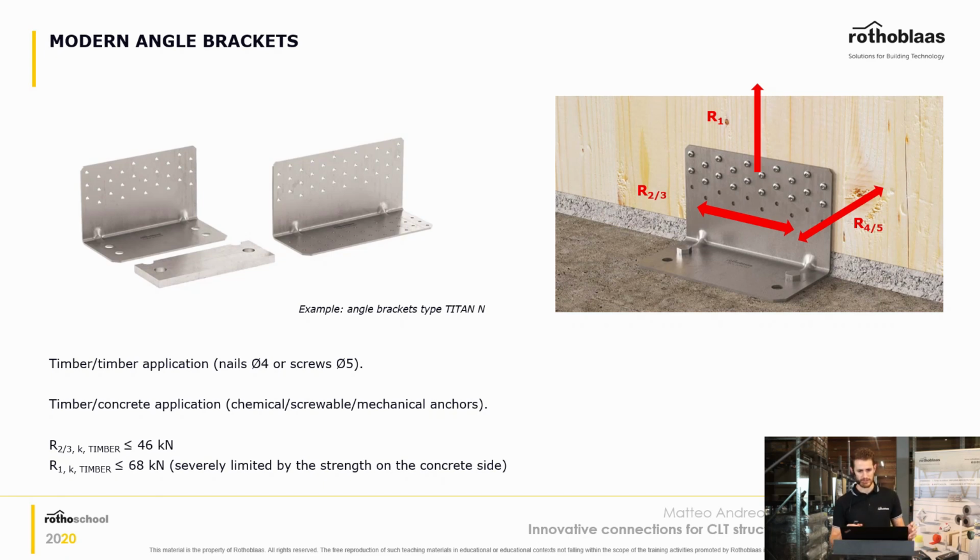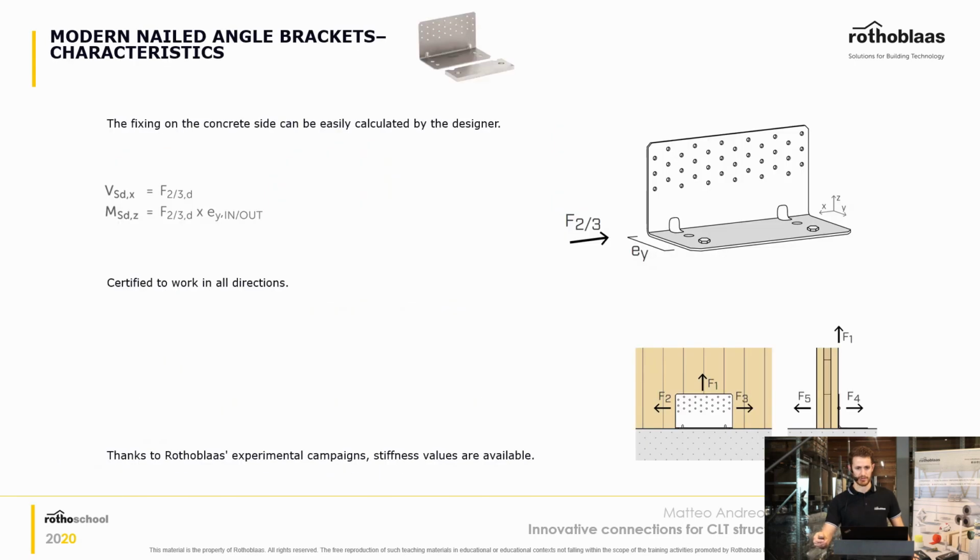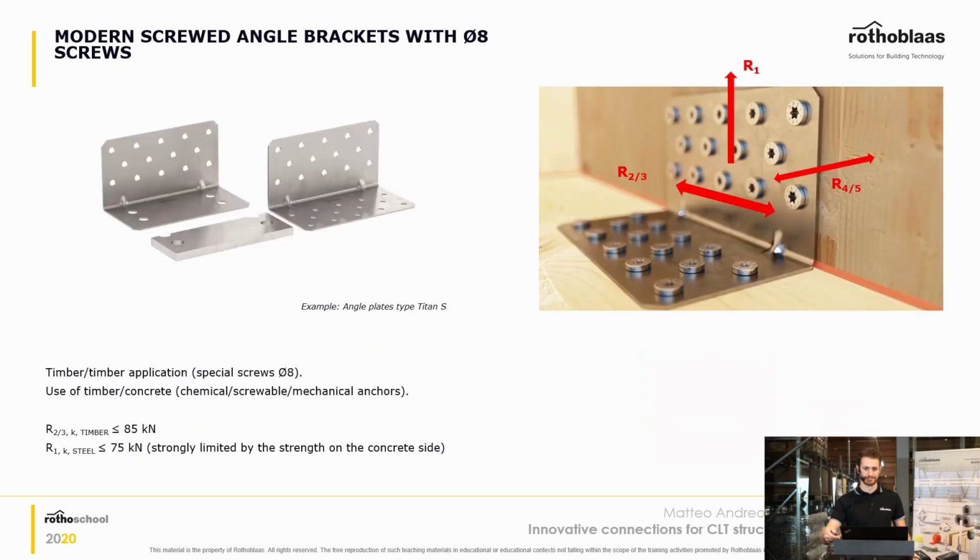The steel tends to bend up and fail, and therefore by adding this base reinforcement, it's possible to increase a lot the resistance of this connector. And of course you can use exactly the same one to withstand the shear forces.